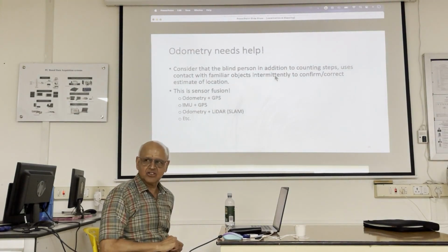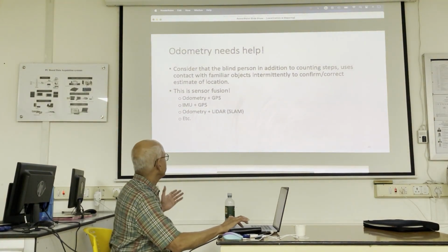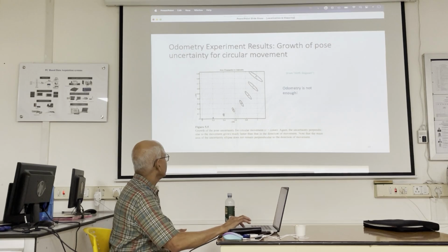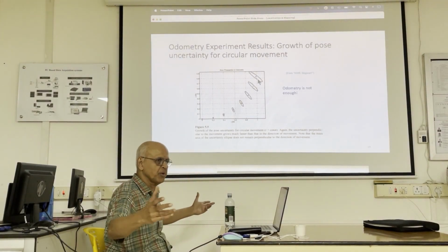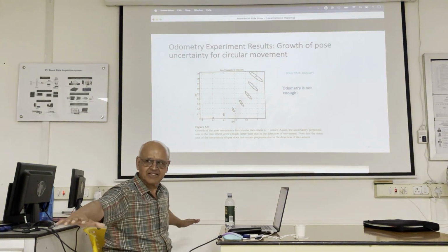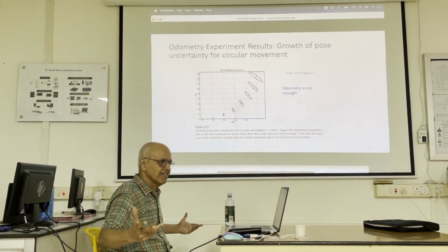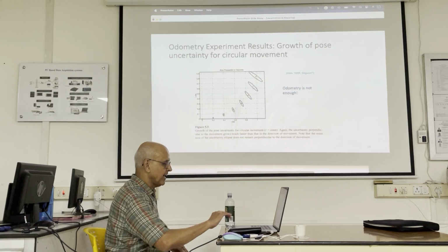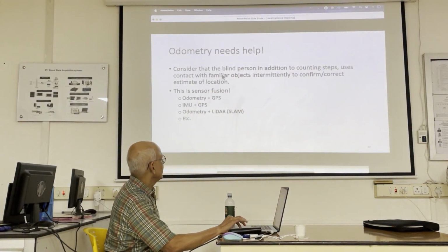Because if we depend on odometry for too long, you'll be completely lost. You could be anywhere. See, this ellipse is growing and growing and growing, so the Gaussian is getting shorter, but it's getting wider. And eventually the Gaussian will get washed out, which means that you could be anywhere. And you don't want that. Therefore, you want to refresh.